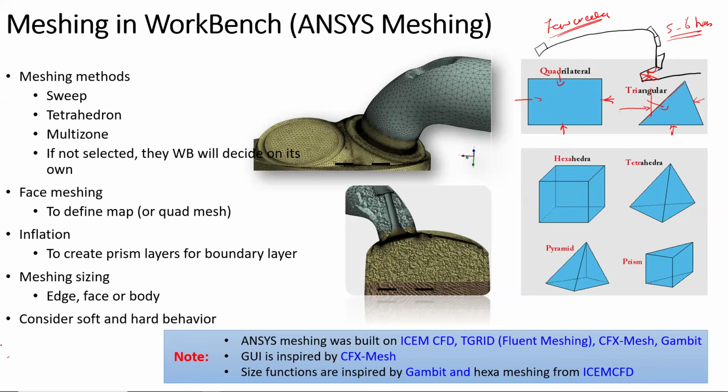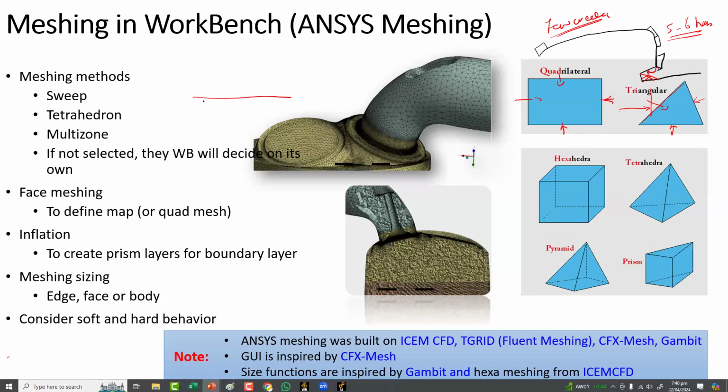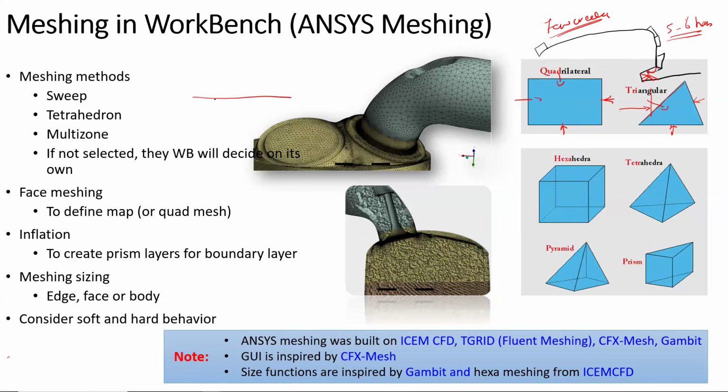Now the problem is when you are talking about a boundary layer mesh, for example here this is a flat plate. This flat plate will have a boundary layer here. To resolve the boundary layer, we need more nodes towards the high gradient regions, and the elements should be aligned to our geometry and flow. Maybe we should be resolving at least 20 locations.